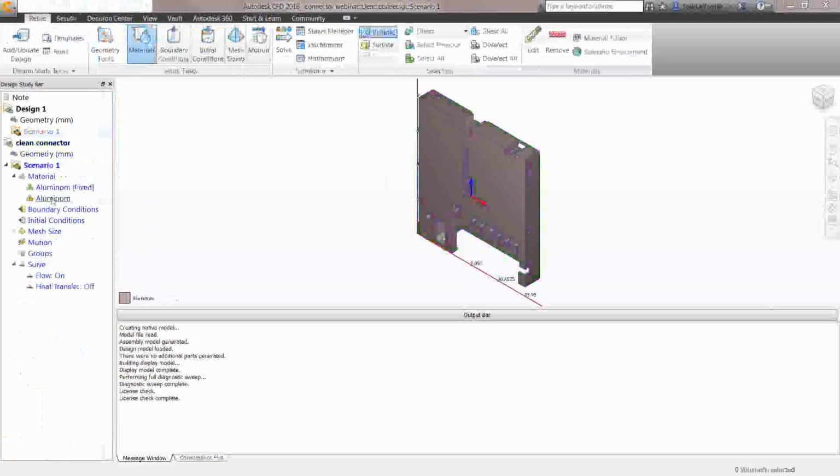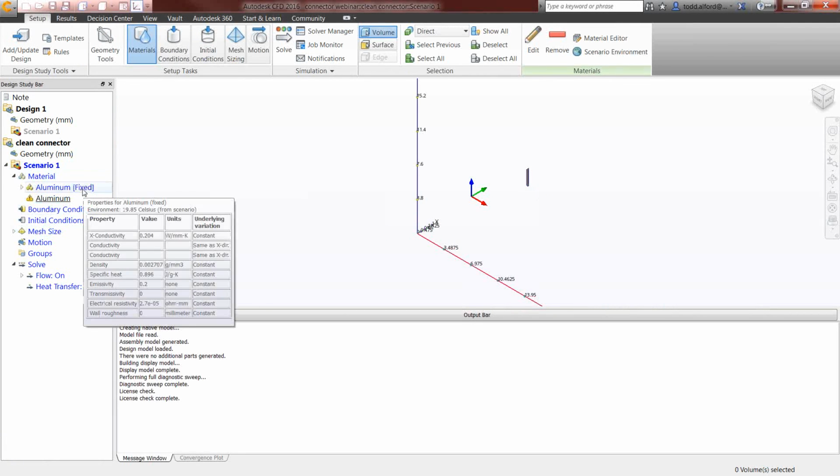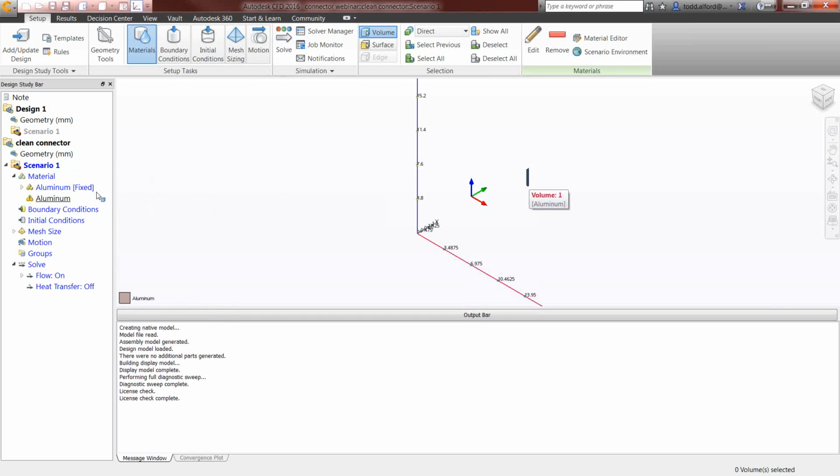Now I have a part that it doesn't know where to apply something, and really until I start hiding things and looking for where things are, because I got rid of 2 or 3 parts and now I'm down to just 2, and this is a new part, so it doesn't get, well, it actually got the aluminum, but I end up with something hanging in the tree. So when you're doing that update, you always need to make sure that everything's set.